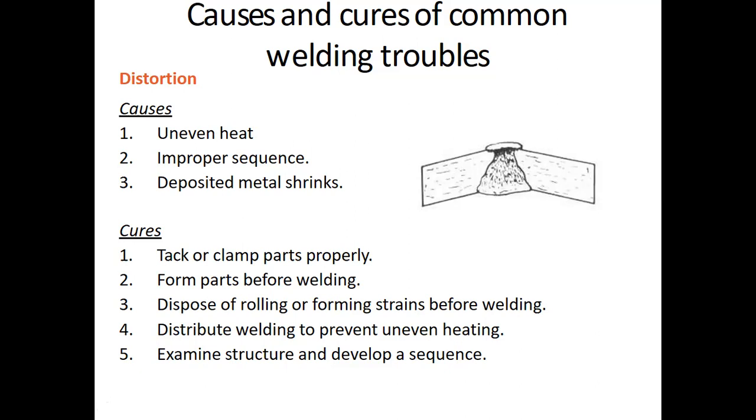What are the cures? How to avoid it? Tack or clamp the parts properly, right? Just as we have done for the warping case. You can clamp them properly to avoid this kind of defects. Form parts before welding. Basically trying to prepare that edge preparation.